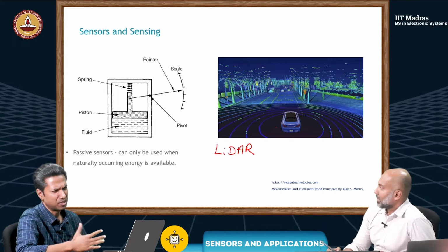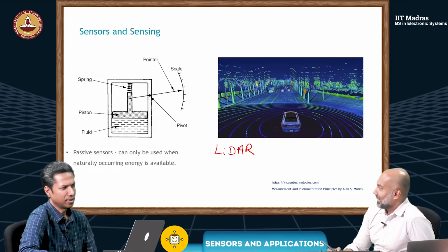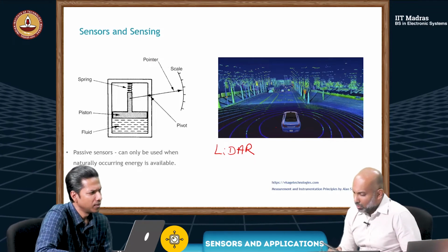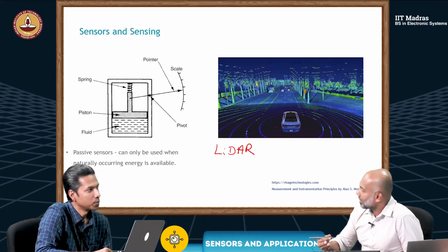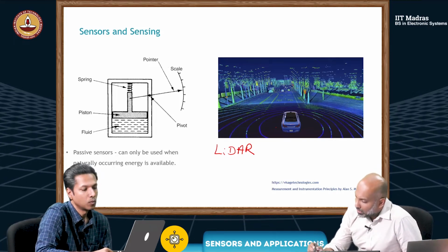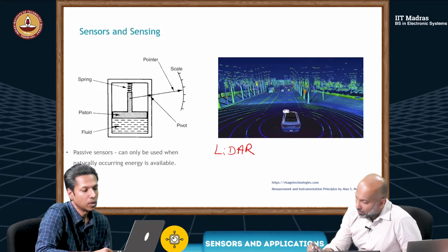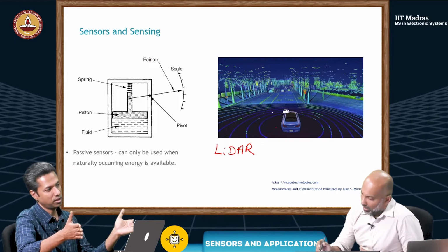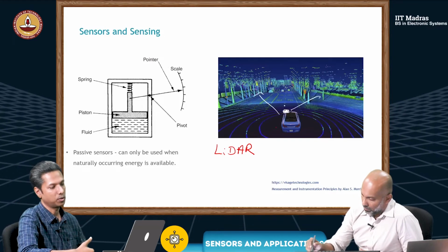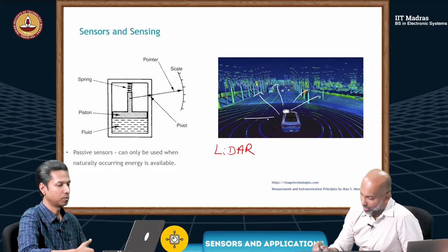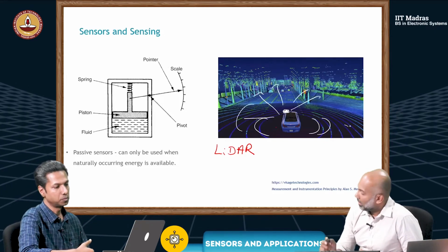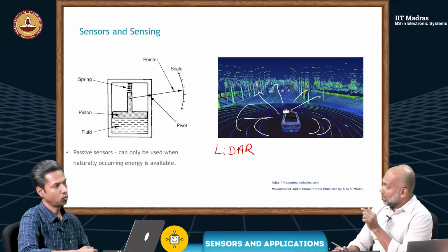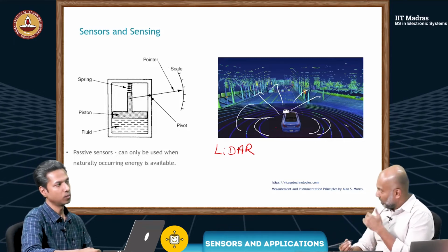It's a little bit complicated to understand, probably. Actually, I don't think it's difficult to understand. The basic idea is light detection and ranging. Let's say this car has some device that has a source and sends out light waves, all around actually. You can see here, these things, and the light wave reflects back. Now there's also the time of flight, the time between transmission and receiving.